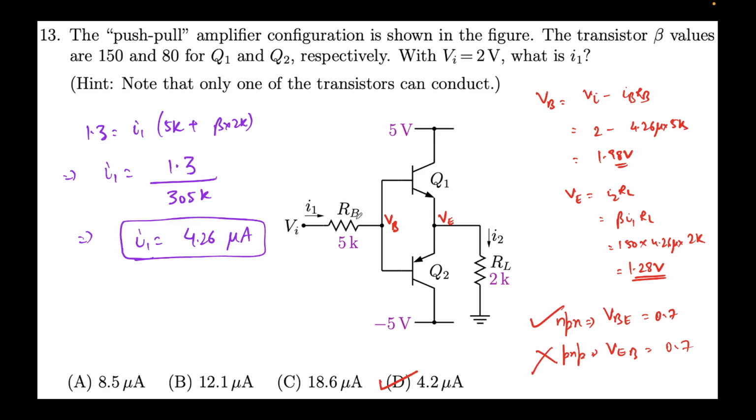Okay, we can also see actually what's the value of VCE. So VC here is 5 volts, right? And VB is around 2 volts, right? So VC, this is N, so N is at higher bias. So remember NPN, right? So N terminal is at higher bias as compared to P, so this is again reverse biased. And VCE, as we see, is 5 minus 1.28, that will be 3 point something. So this Q1 is indeed in active mode. So that's what we had confirmed just after obtaining the values.